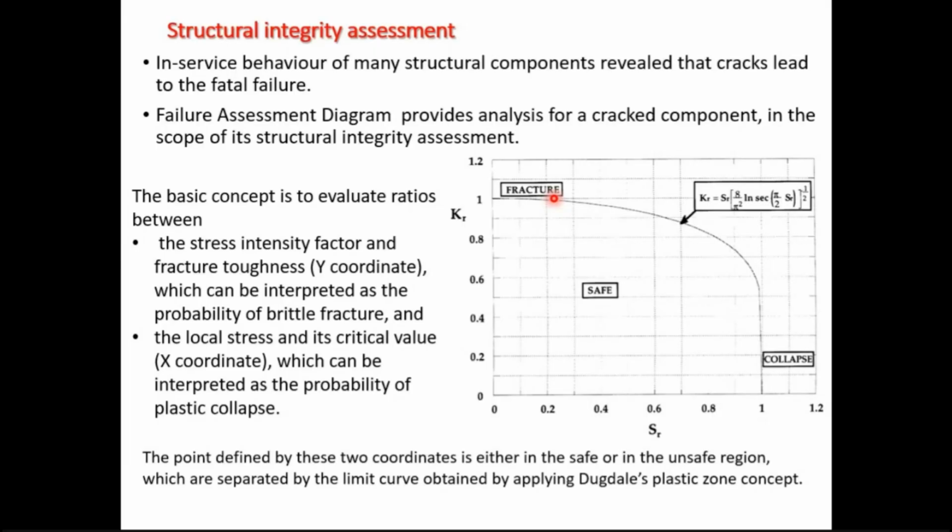Based on these two measurements, we finally concluded that the acting stress is, as you can see here, in the critical point about 115. From that point on, we could use the same procedure to calculate coordinates and to position this critical point, once again, in the safe region.